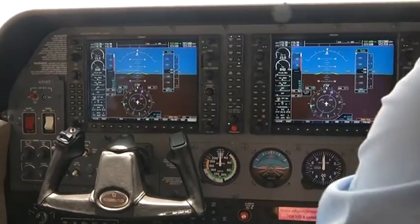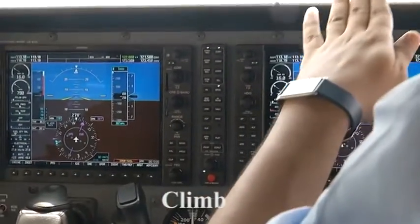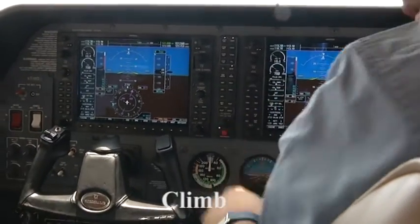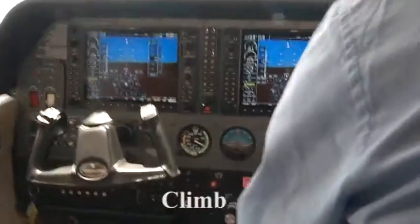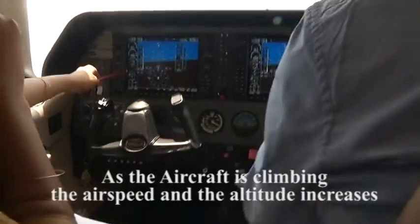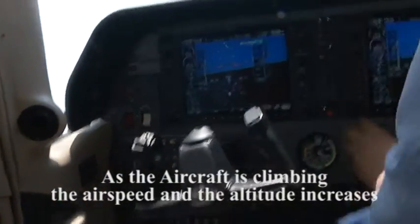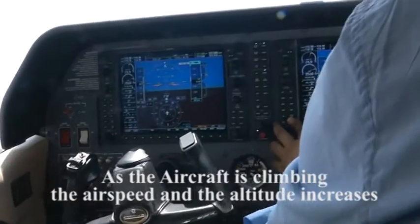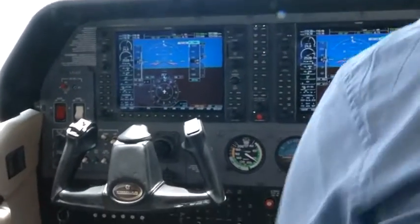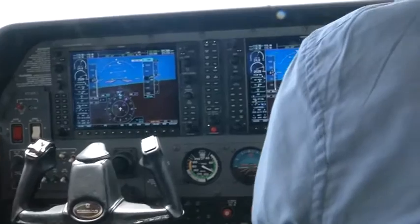Now we can increase our throttle, airspeed alive. After airspeed reaches 60, then slightly backward pressure. Okay, the nose goes up. This is a climbing motion. This is the airspeed. The miniature aircraft on the artificial horizon can be seen. The aircraft is stable, so the miniature aircraft is also stable on the gauge of the artificial horizon.